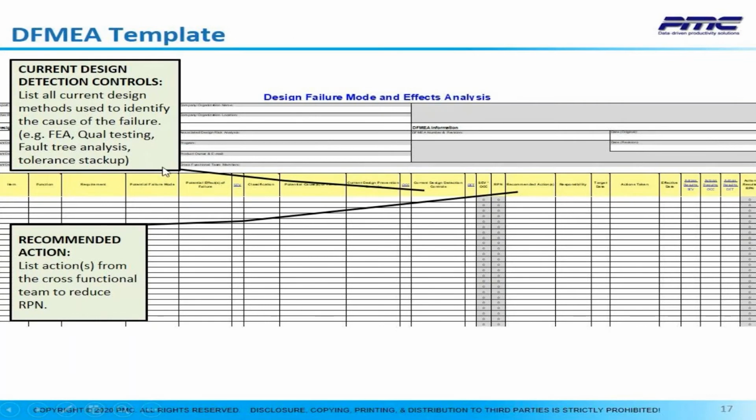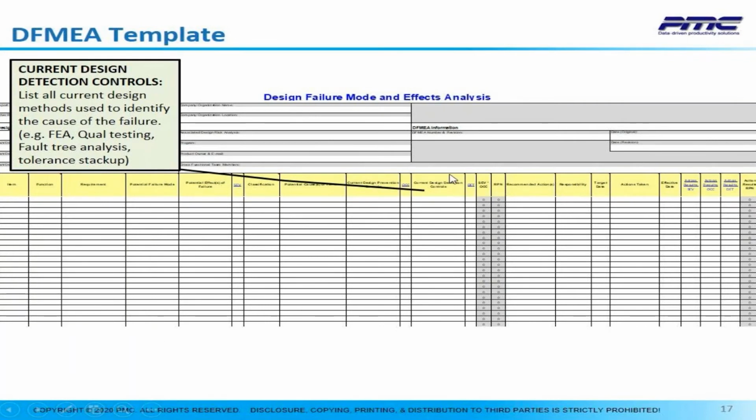At this point, up to here, including the severity, occurrence, and detection ratings, the criticality and the RPN will be calculated. So based on the methodology that your organization will be using, for example, currently we're using RPN. We also look at severity 9 or 10 and high RPN. We focus on the top 5 or top 10 RPNs to be mitigated first, and that completes the entire DFMEA up to here.